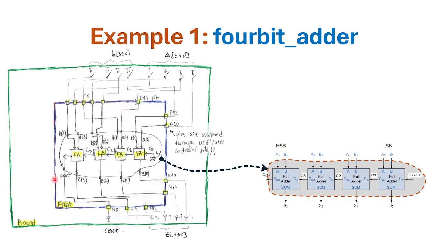In a more complete block diagram, I would show that structure, but I would also show the connections of the input and output ports of this entity to different pins of the FPGA, which sits on the board, and these pins connect to different components on the board, such as slide switches that we use to input values for A and B that we want to be added, and then LEDs that we want to drive using the outputs of this 4-bit adder, where they carry output.